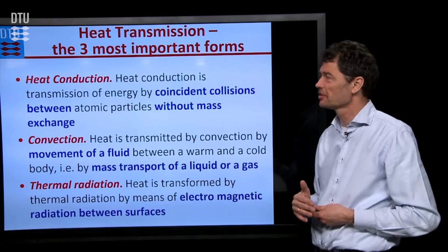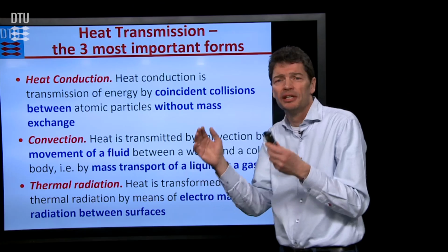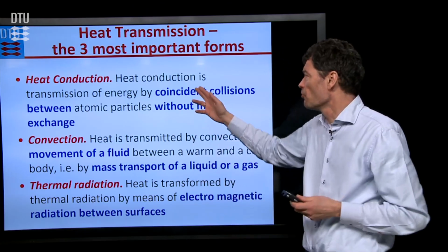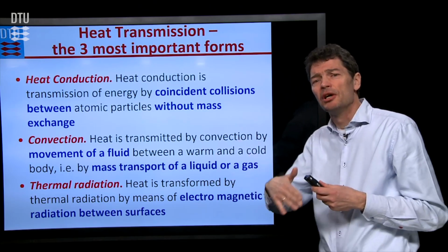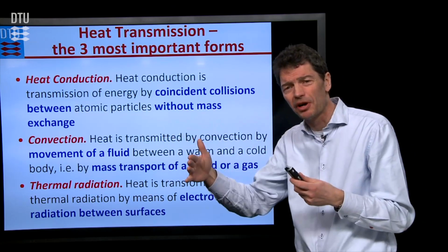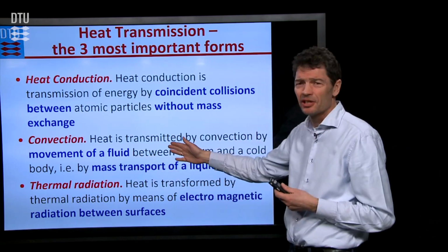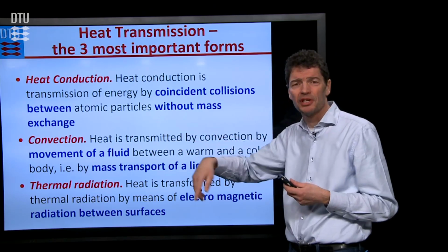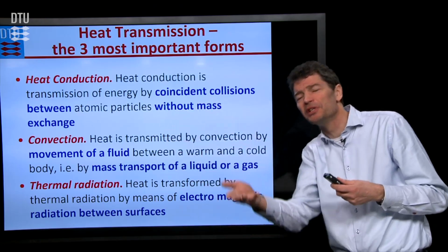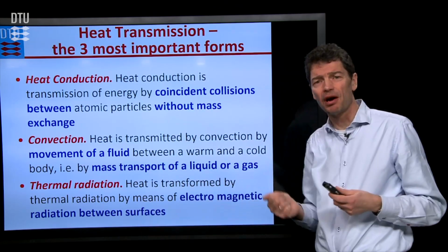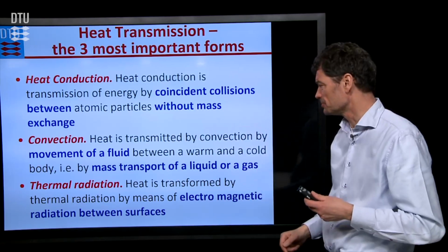They have separate lectures, I've said already, but just very briefly, heat conduction is transmission of energy internally in a material where the collision of atoms in the materials, vibration for instance, will move heat from warmer to colder parts without causing really a transmission of material as such. Unlike in convection, then you have movement of something in a fluid like a gas or liquid. Then with the movement also comes a movement of heat that follows with the mass that flows around locally in an environment. That's convection.